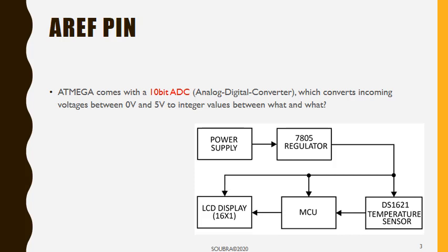All right. Now my question to you is: everyone's following till now, all right? So the physical grandeur, I don't know how to translate it in English. Let's call it element for now. So the physical signal that I'm trying to measure varies between 0 and 5 volts. All right? Now I want to translate it. I want to map it to some numbers. The hypothesis here is telling me I dispose of 10 bits in order to translate this continuous signal.